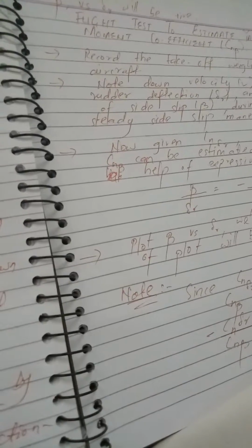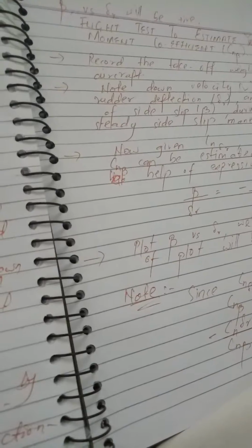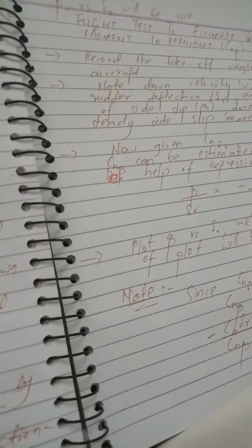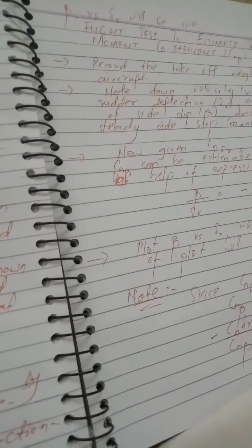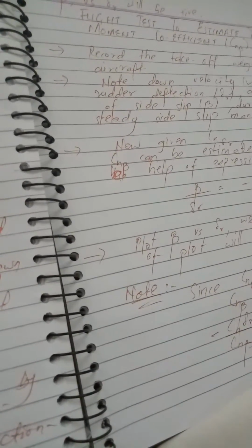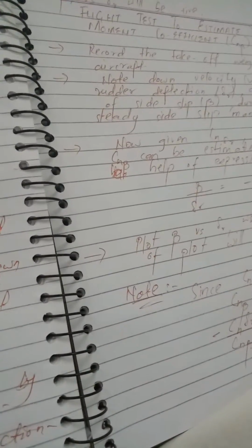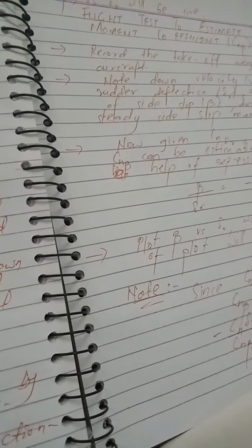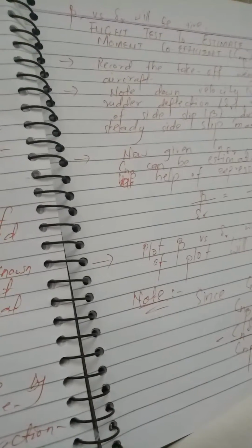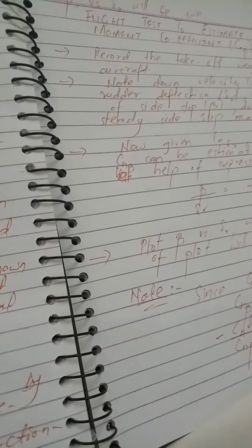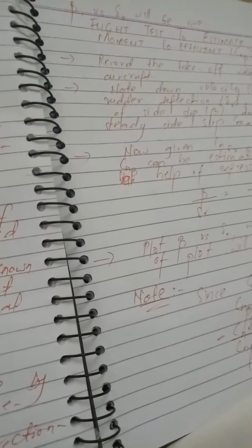So the dominating factors would be Cn of beta and Cn of delta a, because of the side slip. Obviously beta is essential, and we can say that the control angle and the aileron stability are the major or dominating factors, and the rudder is actually counteracting these two just to balance off the stability or the instability, if it's stronger.